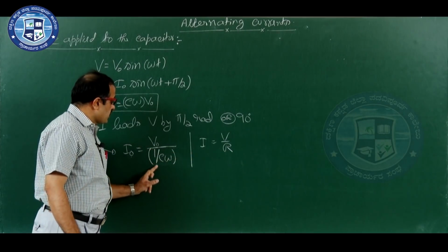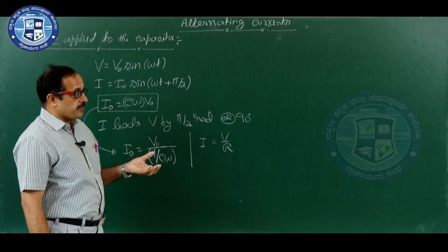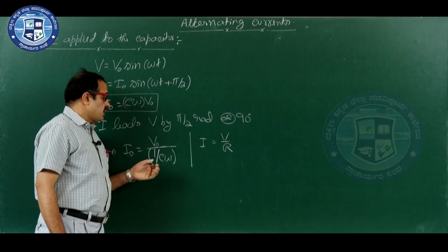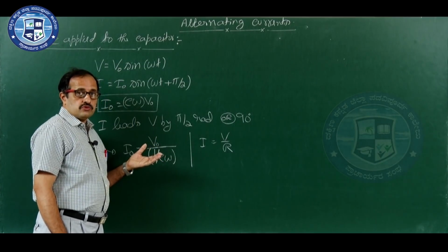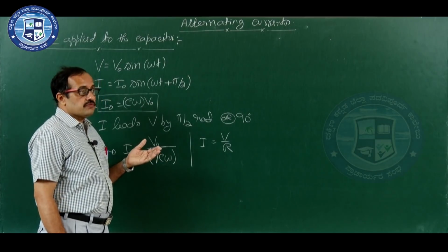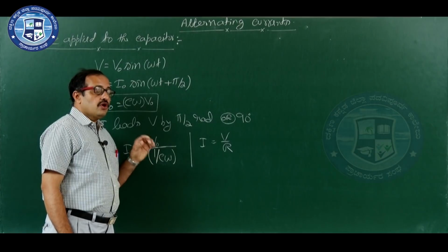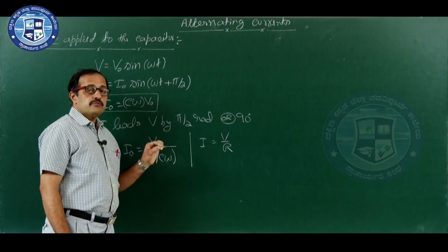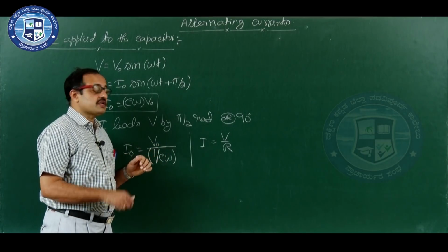Therefore, this term in the denominator we can say is the resistance of the capacitor for the flow of AC, but again we face the problem as in the case of the inductor. What is the problem in the inductor? I said while discussing the inductor, when alternating current flows through the inductor, it opposes it, but it never produces heating effect, it never consumes electrical energy.